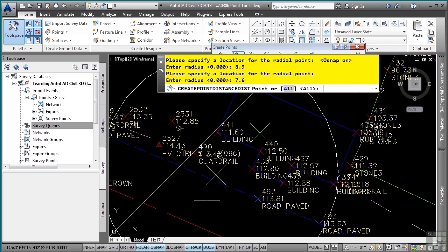These points are the intersection of those two circles that were created. They are imaginary circles, so what you have to do is simply click somewhere near the X that you want to pick. Or if you wanted to create both points, you could simply select the All option in the command line window. I'll simply pick here.